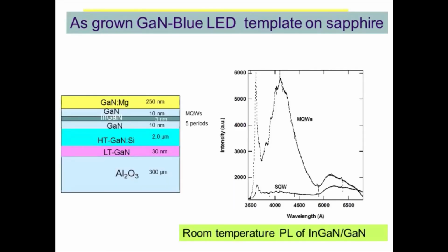And for any semiconductor, you know that the PL, photoluminescence, is a very important characteristic technique based on which you'll be able to understand the status of the band gap. So here, this is a typical LED structure. The substrate here is Al2O3, and you have the low temperature gallium nitride to suppress the lattice mismatch occurring at the interface, because aluminum oxide has a different structure and gallium nitride has a different structure. They also use silicon carbide as the substrate.